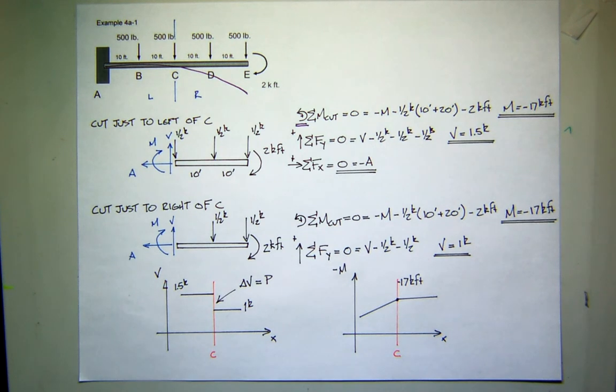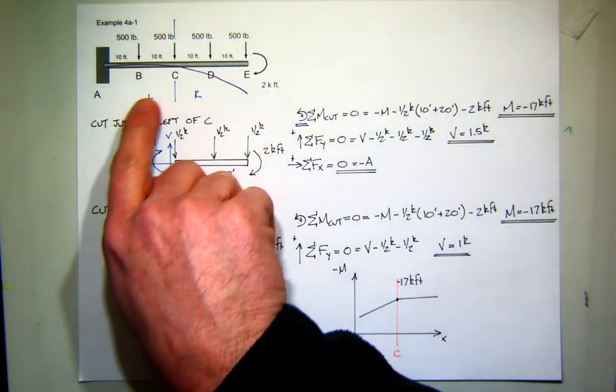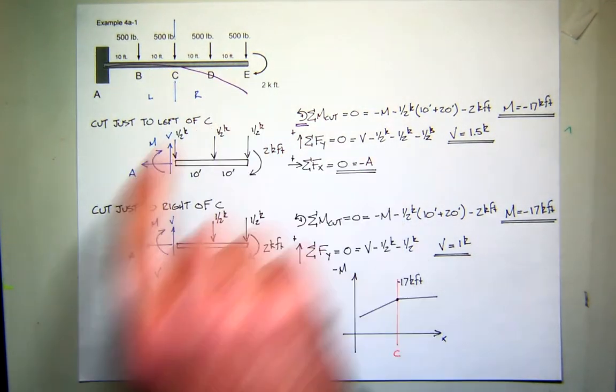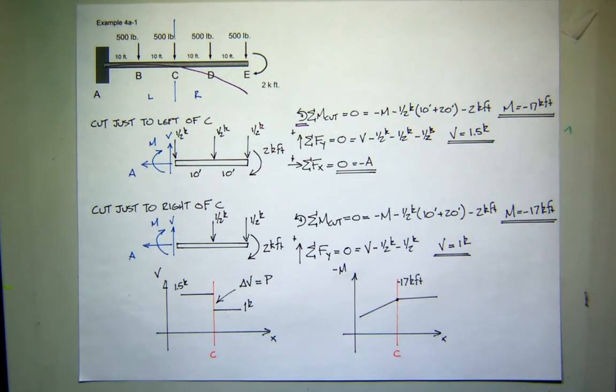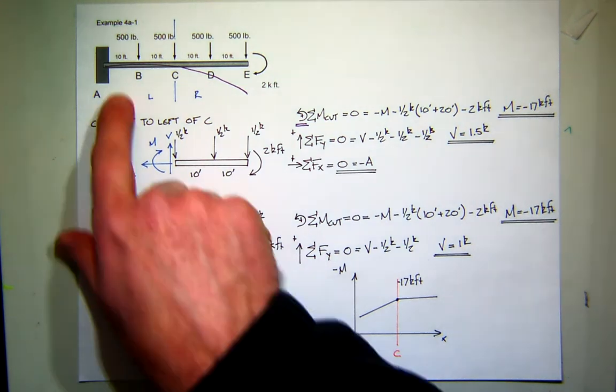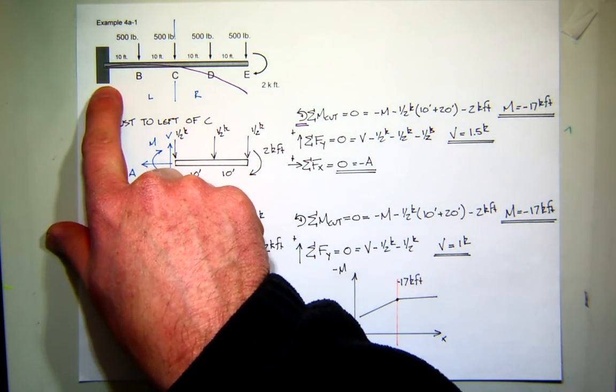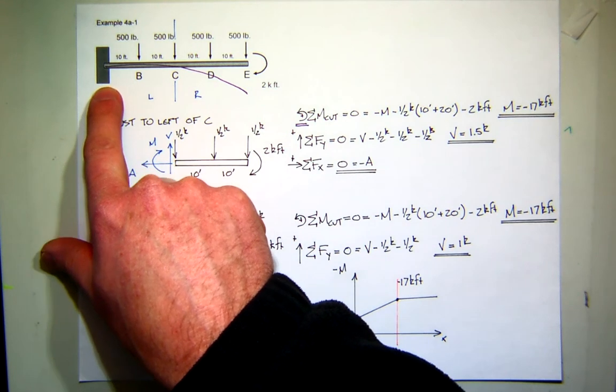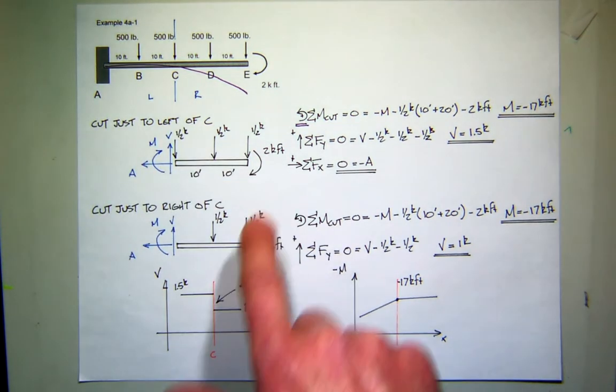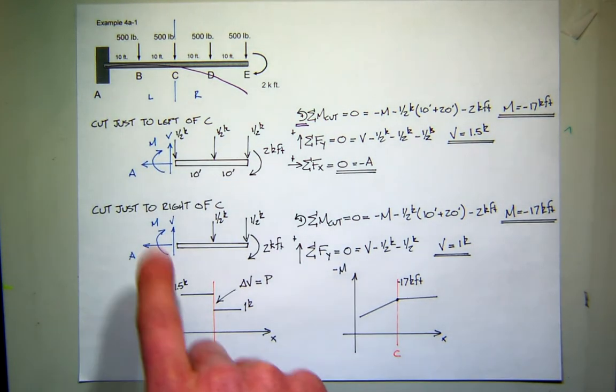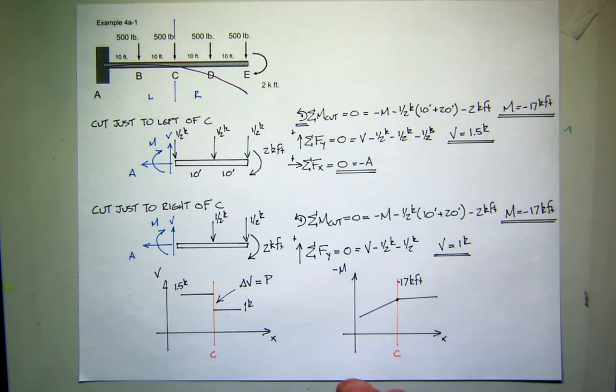I know we're just getting started, but I wanted you to start thinking about how shear force and bending moment are going to vary along the beam. If we extended our plot for the entirety of the beam, it would just keep stepping up. Which one? Shear. Yeah. And we haven't included the reaction shear. So we would start at some shear value and we would step down all the way across the beam. So the whole plot would be a series of steps.